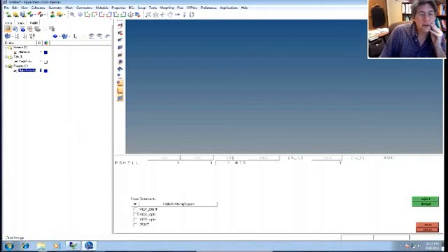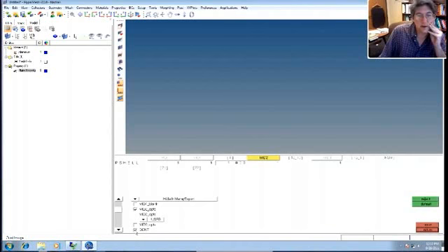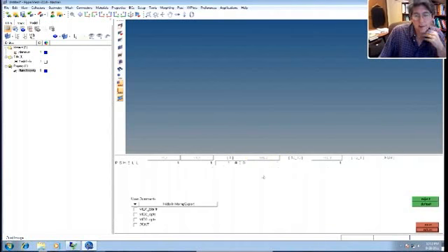You can see if we hit MID 1, we can add different option fields. You can do a continuation card and put in the next line. That's optional, but we won't do those, so we'll just leave it at the basic one-line P shell definition. We won't use the other optional lines, okay? All right.